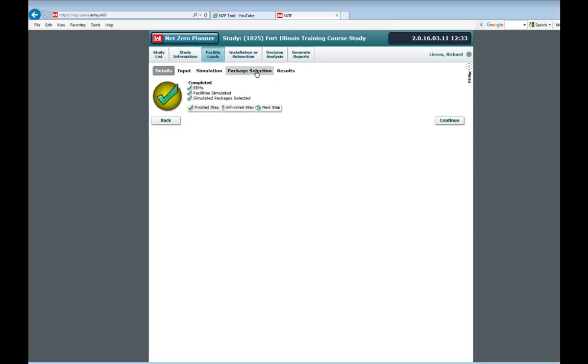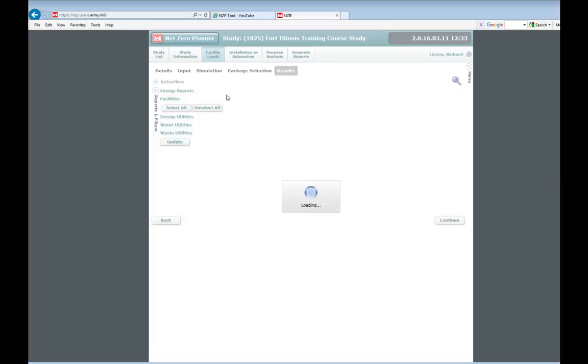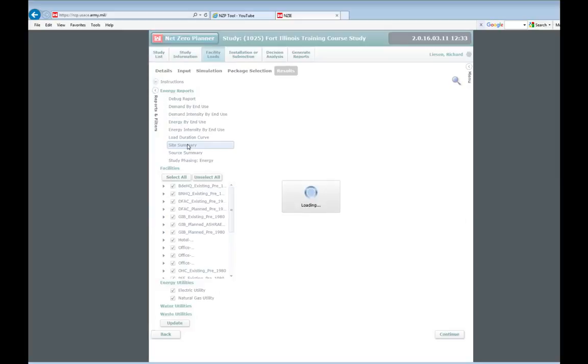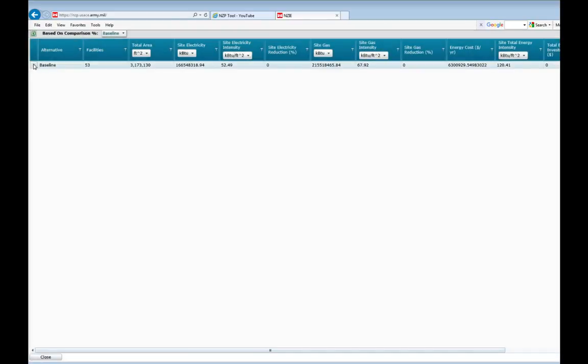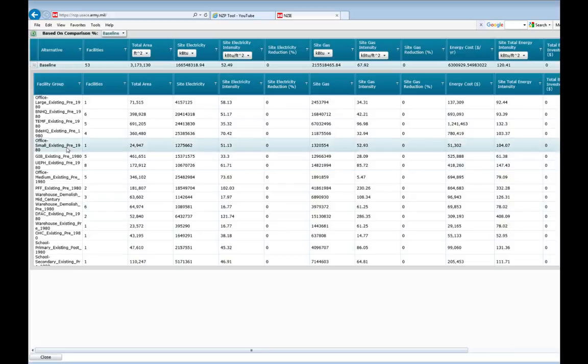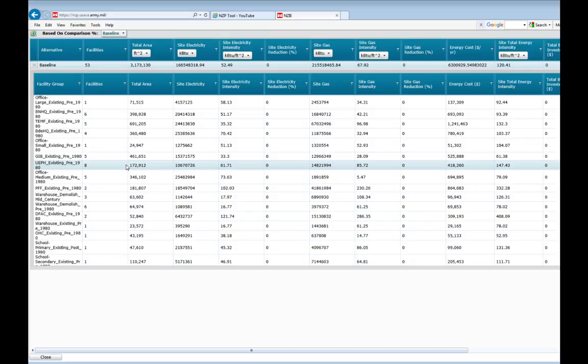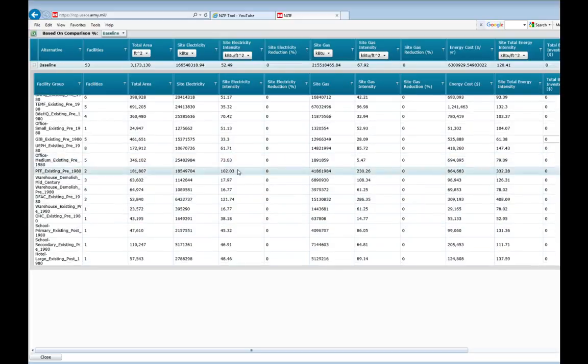But we also can go back to our models, look at those results, and then come back here and think about the building stock that you have. Did I capture these pre-1980s or mid-century models? Is it extra leaky compared to what I'm simulating? Is the envelope better or worse? Is the equipment better or worse than what I'm looking at? Those are the types of inputs that we want to look at as we're looking through this building list, and see how they compare to that average. And does it make sense if it's higher or lower?